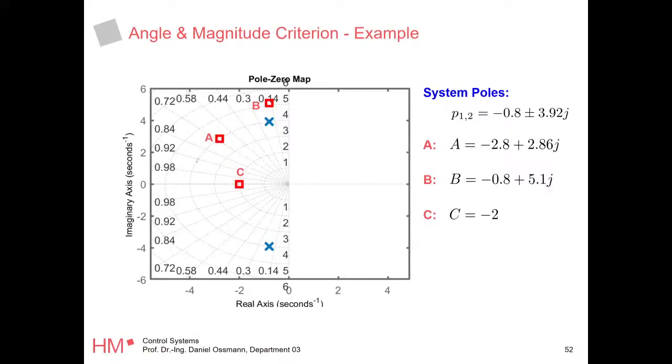So the natural frequency, you see these circles here, right? These are the natural frequency, and our system is exactly at 4. So we want to move along this circle until we hit 0.7, and the lines here are the damping lines. So our design point to increase the damping to 0.7 would be exactly this one. This is where we want the poles to end up. And see, these are the poles of the system at this point.